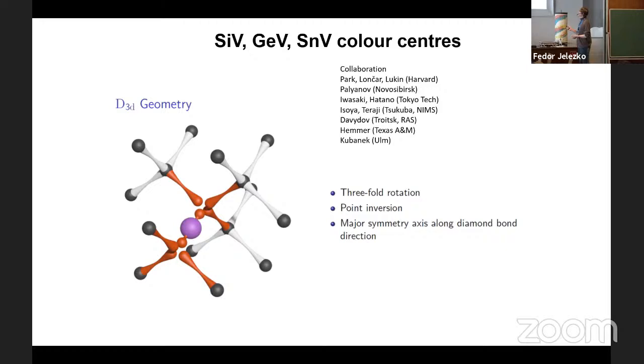This element, silicon, is very similar actually to nitrogen in terms of incorporation, but it's larger. And because it's larger, when you try to place it on a vacancy position, it will not fit very well. And if there is another vacancy nearby, it will shift in the middle between two vacancies. So although it's a silicon vacancy, actually silicon sits between two vacancies. And this is a highly symmetric structure with inversion symmetry.